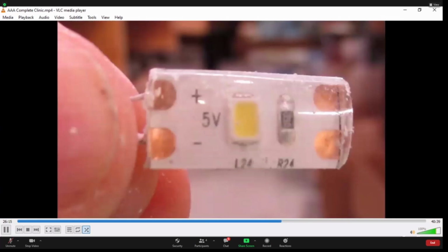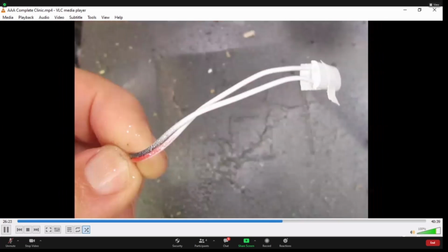I dropped a bit of solder on each dot and tinned the ends of a black and a white 28-gauge wire, and then made the soldered connections. I removed the LEDs from my work surface and placed a spot of masking tape over the actual LED. I then spray painted about 2 inches of the wire around the LED so that the black wire would be less visible when the unit was attached to the ceilings.